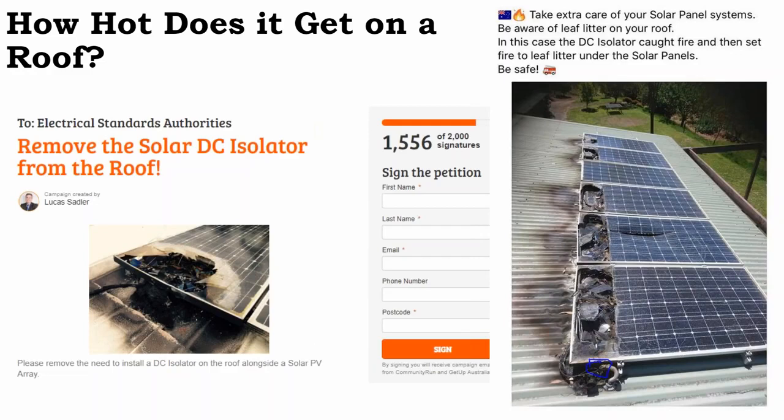Another aspect is debris can accumulate underneath the solar array, and if you get debris accumulating around that box, that can be a fire hazard as well. To the point where it's not a bad idea to budget a little more money and put a metal netting around the perimeter of the array. Most installers don't do that. I'd say it's not a standard practice, although I know solar companies who have it be a standard practice.